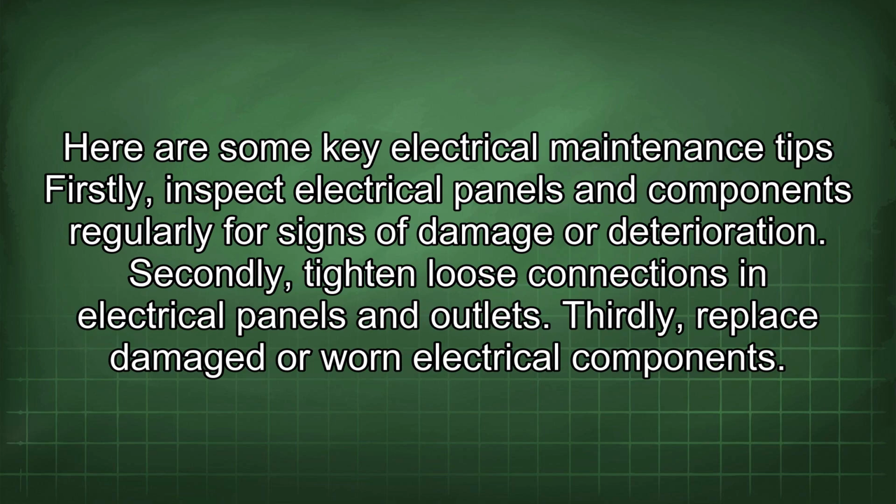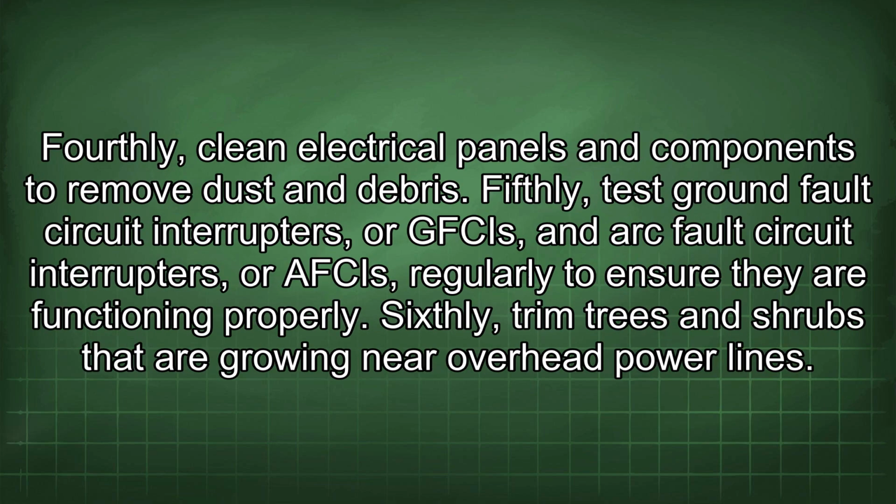Firstly, inspect electrical panels and components regularly for signs of damage or deterioration. Secondly, tighten loose connections in electrical panels and outlets. Thirdly, replace damaged or worn electrical components. Fourthly, clean electrical panels and components to remove dust and debris.